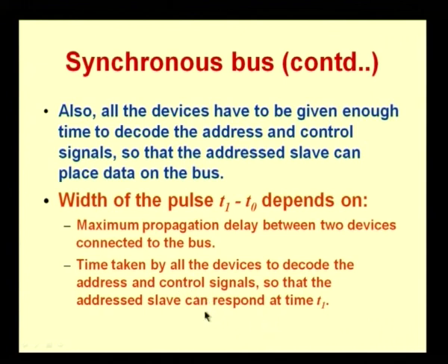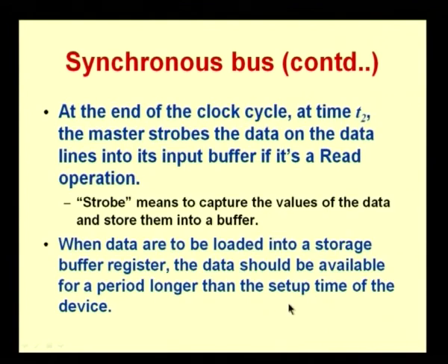Okay, it will take some time to get the data and put it on the bus. So that setup time also has to be taken into account. So t1 minus t0, the width of the pulse, is dependent on these two factors. And at the end of the clock cycle, that is at time t2, we said the master will strobe